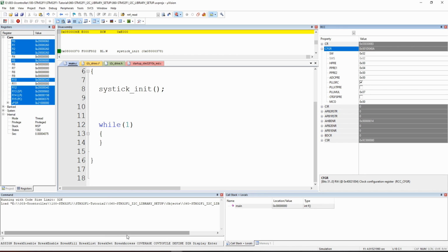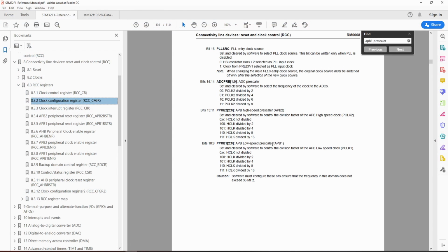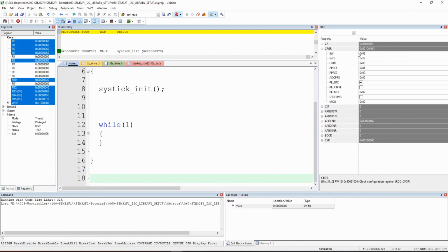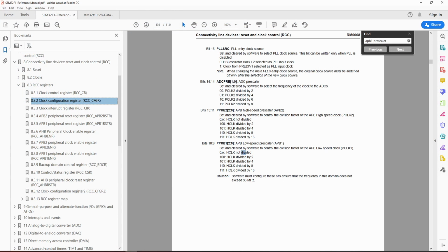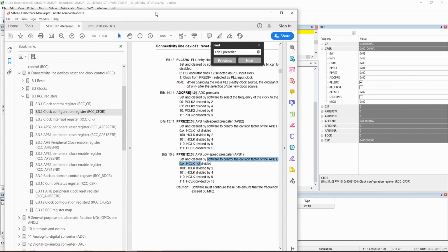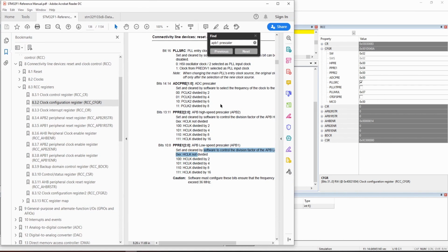And we set which register, and this is the APB1. Let's take a look. Where is the APB1? Okay, let's check again. And this is the configuration register. Ah, yeah, this is the one. Okay, it has been set to 4, so 4 is this one. We have the input as 36 megahertz. Just in case, always checking this parameter is very important to be sure about it.